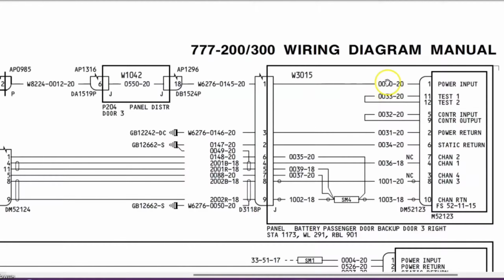Now we have to find out from where this wire is coming and where this wire is going, and the contact number. In another condition we will take an example where we just have the contact number for this plug. We have this particular plug and the contact number 1 has to be changed. So we will find out which wire number is there, which bundle number, and all the different things, and also how to find the part number for this. If we are replacing the connector, what will be the procedure, and how to find all the other details.